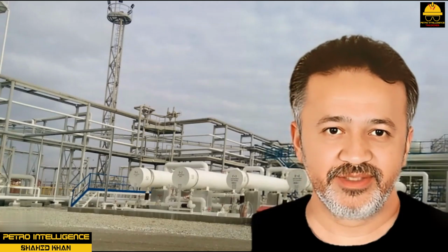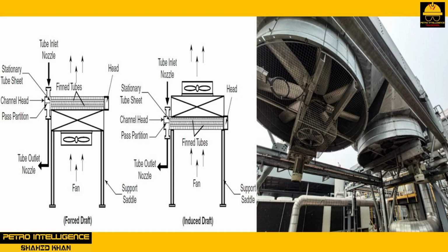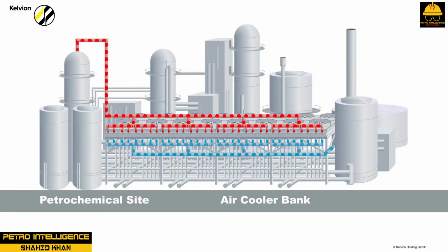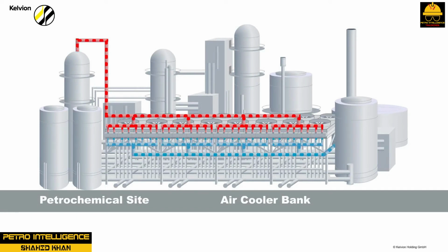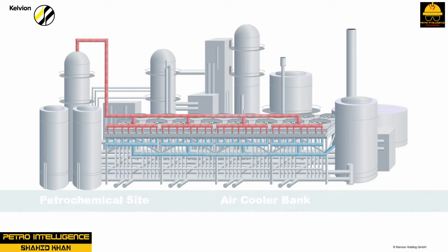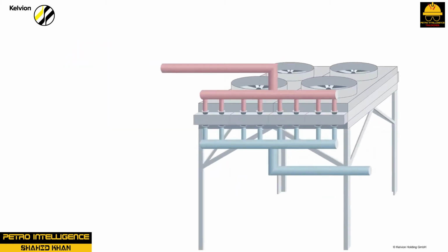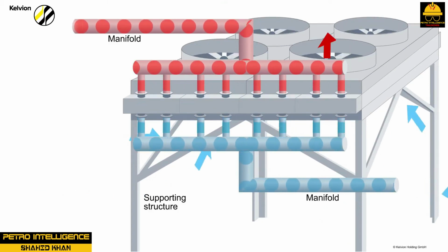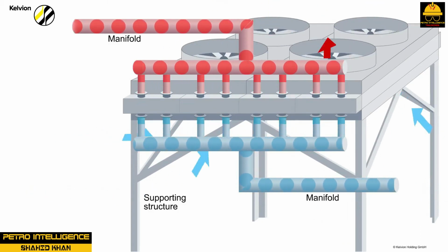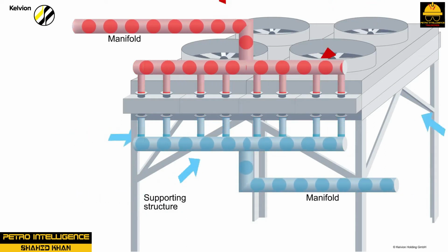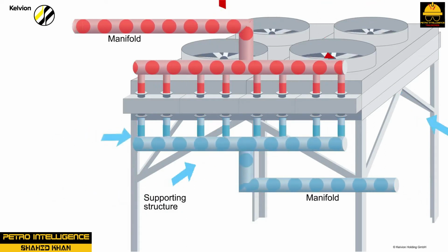Air-cooled heat exchangers. A different approach to heat transfer occurs in the fin fan or air-cooled heat exchanger. Air-cooled heat exchangers provide a structured matrix of plain or fin tubes connected to an inlet and return header as shown in picture. Air is used as the outside medium to transfer heat away from the tubes. Fans are used in a variety of arrangements to apply forced convection for heat transfer coefficients. Fans can be mounted above or below the tubes in forced draft or induced draft arrangements. Tubes can be installed vertically or horizontally.